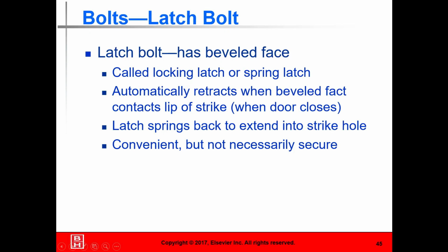Called the latch bolt, or a spring latch, it automatically retracts when the beveled face contacts the door. The latch springs back to extend, convenient but not necessarily secure. This is your typical door bolt, as we look at. So when we close the door, it strikes in. When it clears, it pops out to keep you from opening it again. Again, a very simple locking mechanism.